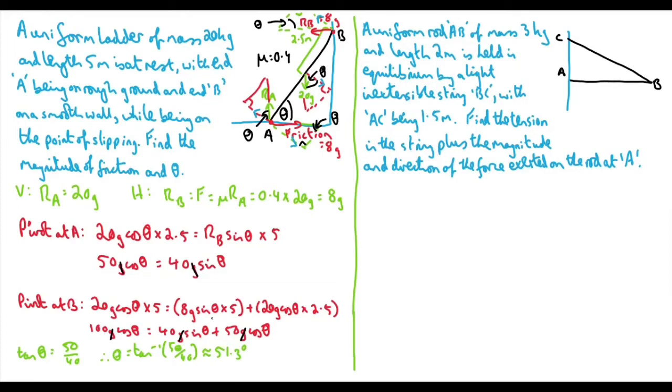Okay, so again, that's just how, if we have something at a diagonal, we can potentially take components before we start taking moments, because the distance and the forces for the moments have to be at right angles to the rod, the beam, whatever it is.